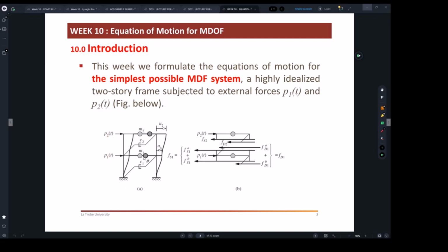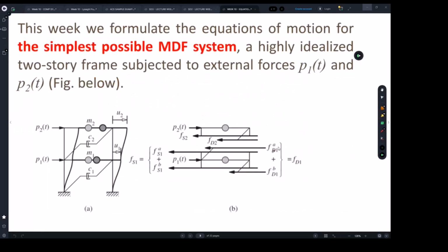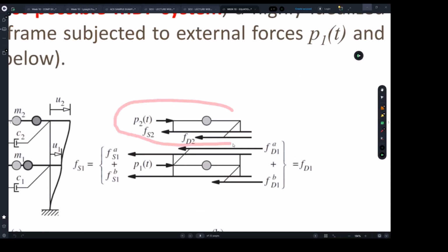So once we all agree about this definition, we have two masses that are freely moving left or right, independent of the other structural elements within the building. Then for such a structure, we can use the skills we used many years ago when we sketched the free body diagram, and we can do this for whichever floor. What we're showing here is that we can look at the second floor, cut at this level, just to have it independent from the rest, and then start drawing a free body diagram.